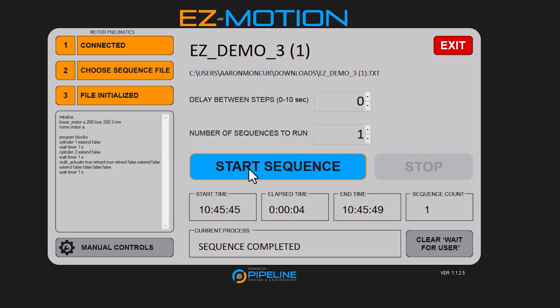At any time, a user can click the Stop button, which stops the system from executing the balance of the program. Note that unlike the physical emergency off switch, the Stop button in the HMI will not de-energize the system. It will not terminate the air supply, purge internal pressure, or cut electrical power.